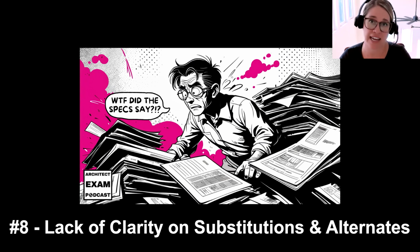So without me specifying that specific expectation of performance, I had very little to stand on to reject this contractor's suggestion of an alternate. The solution to this is to establish a clear criteria for an acceptable substitution and a defined approval process for an item. So when you want to use language that says "or equal," always list a critical performance characteristic alongside it. That way, you're really requiring what that substitute or alternate must meet.